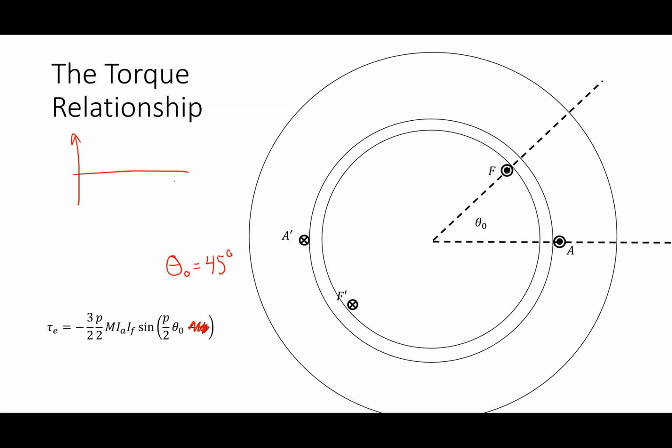The basic thing is the angle of the rotor at the beginning of each period. So if I use this thing as a motor, I have to have controls to go with it, because I have to be able to figure out where the rotor is at the beginning of every period. How would I figure that out?